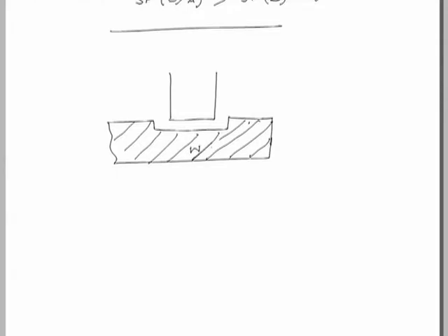So, sparking takes place here. Now, because of this sparking, not only will the work material get eroded from this portion, which will go as debris in this process, but this spark at the same time will cause some erosion on this tool face as well.